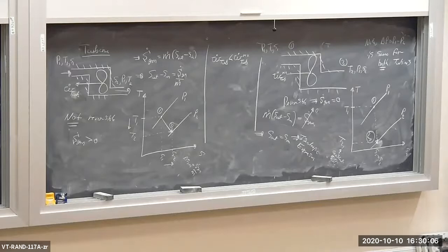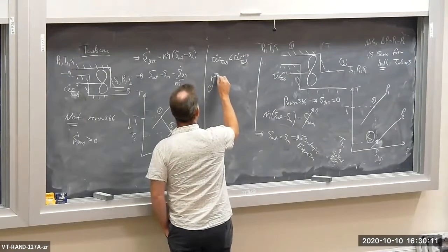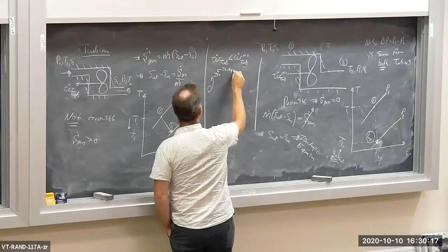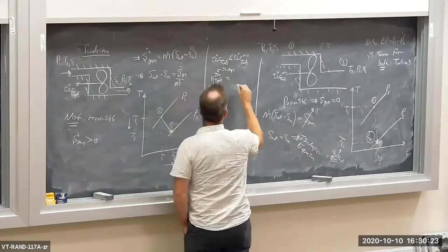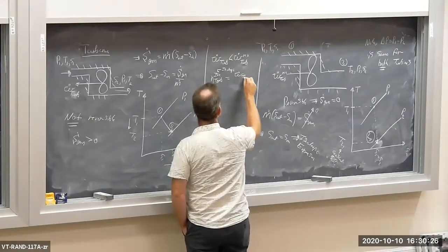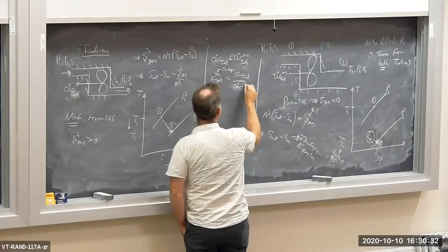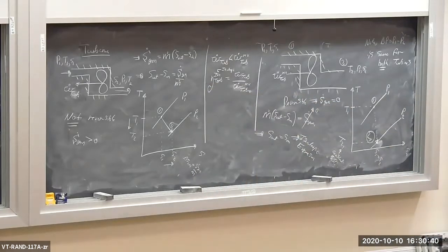So this allows me to develop an expression for efficiency. Eta isentropic turbine is equal to the work or power produced by the actual turbine divided by the maximum possible, which is from a reversible turbine. So the isentropic efficiency for a work-producing device, a turbine, is W dot turbine over W dot reversible turbine.